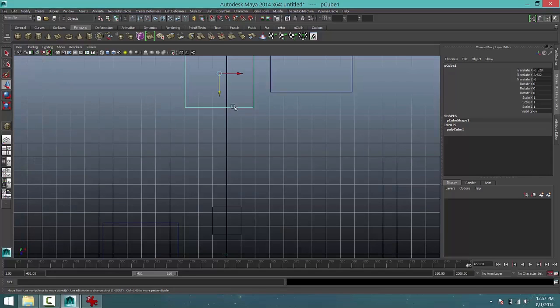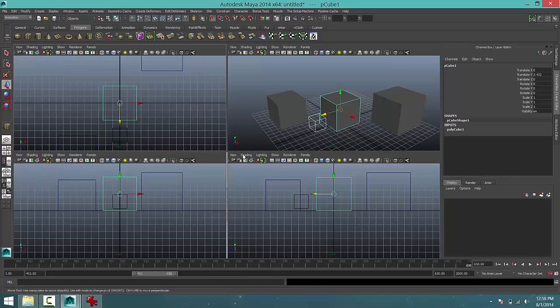So this is our top view, and I want to try and make this object come to the origin. Before I could have been here, but then as I snap to a grid and then I move, it aligns to each grid as I drag, and then I can also drag this way. And then when I get to the center or the origin, I'm sure that I am at the exact origin, not a few units to the left or the right. I'm sure I'm at the exact origin because I've snapped to the grid lines.